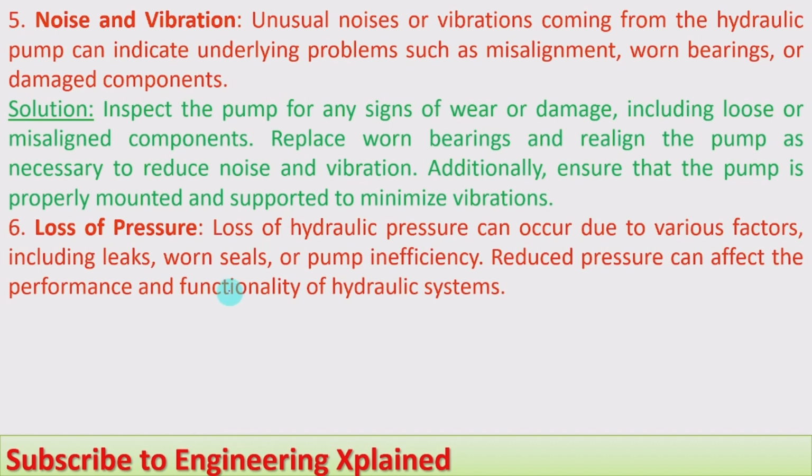The last one is the loss of pressure. Loss of hydraulic pressure can occur due to various factors, including leaks, worn seals, or pump inefficiency. Reduced pressure can affect the performance and functionality of hydraulic systems. Here, the system will not perform the required function if the pressure is low, and that will reduce the efficiency also.